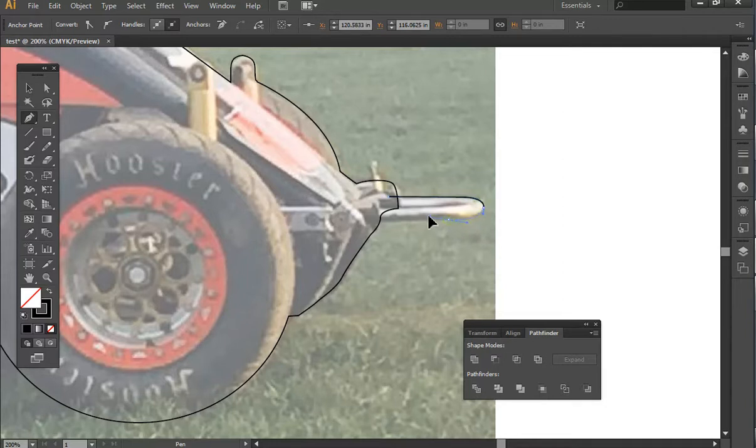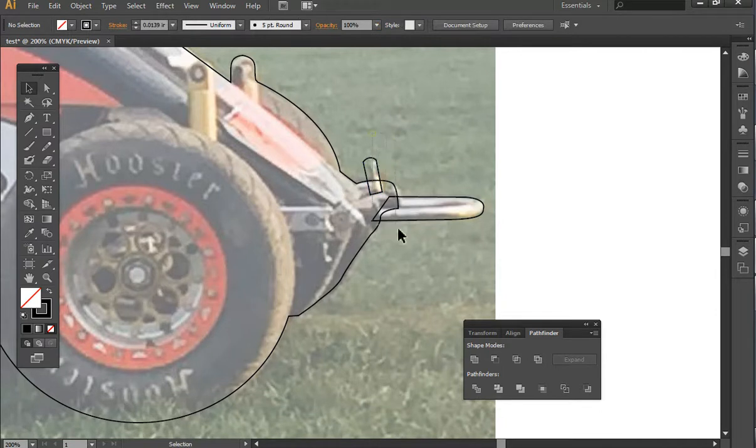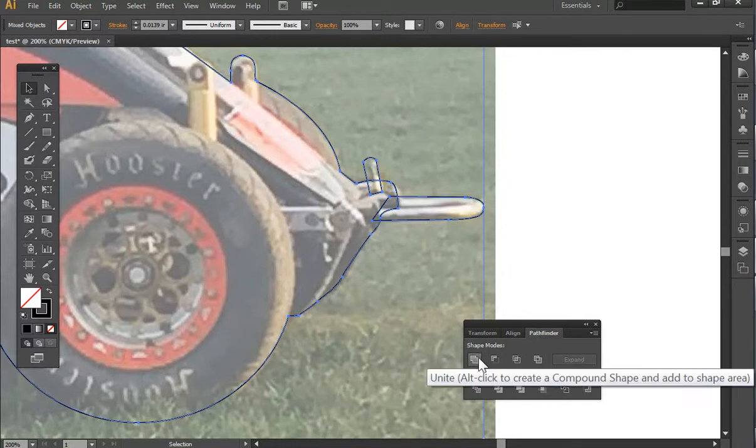Alright. We're just using that pen tool again, and we're making objects here. We can probably capture this too. We're going to exaggerate it because that's a very small detail. If you create something that's too small, when you actually go to cut it, it's not going to cut. It's just going to fall out. So again, I used the bounding box here and just drew over top, and it selected everything, all the objects.